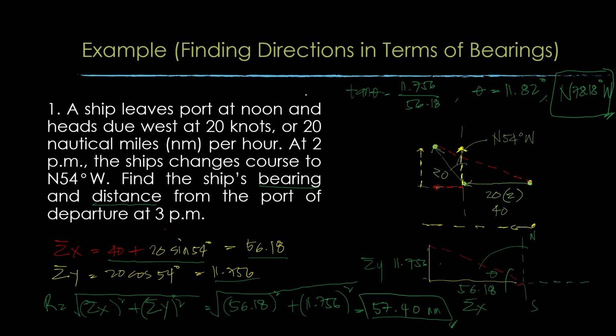In this particular problem, we need to find the summation of your x component and the summation of your y component. Meaning, all the x and all the y from the distances with bearings. Or if this is force and direction. Kumbaga, we're talking about force. But for this problem, we're talking about the distance and the bearing. This is a vector because it has a magnitude and a direction, di ba? Therefore, we need to consider its magnitude and direction.